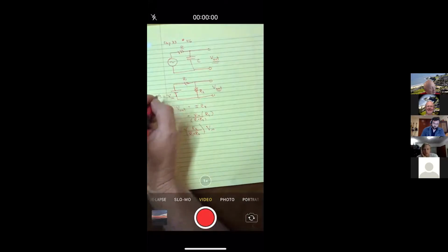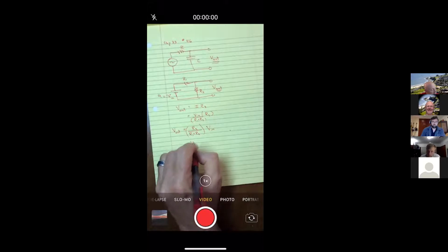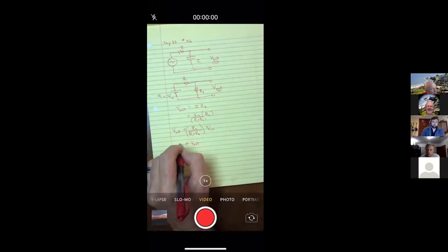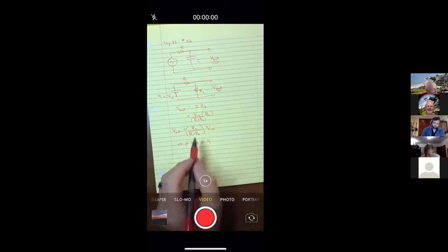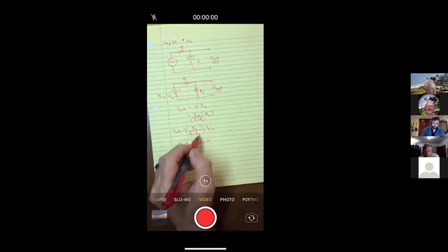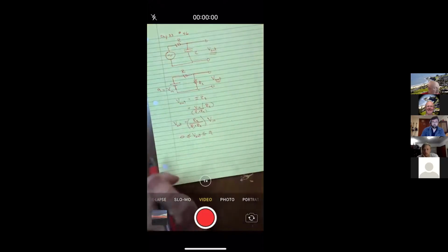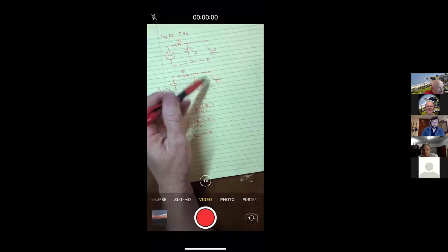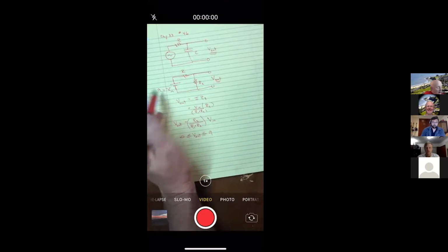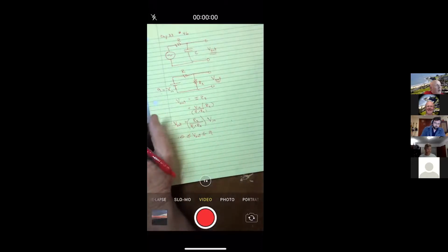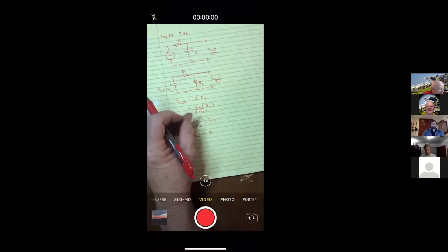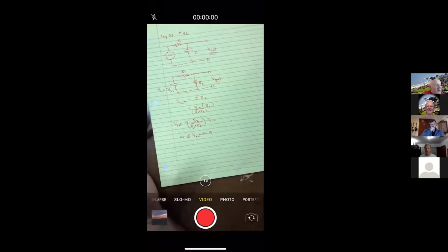So if what you're putting in is, say, 9 volts, you can adjust it so voltage out is anywhere from no voltage, if you had 0 resistance for R2, to 9 volts if you had 0 resistance for R1, because then R2 over R2 would be 1. And so we call things like this a voltage divider because they give you the ability to control that voltage. Maybe a good example of a voltage divider is if you ever try to charge your phone in your car. Your car is 12 volts. You plug it into the cigarette lighter or the utility plug, but you need 5 volts for your charger, for your USB connection that's coming out of there.